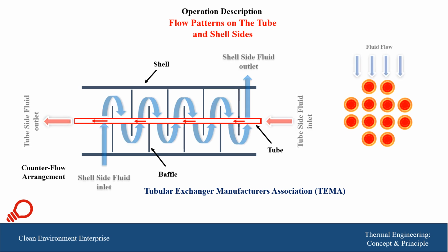Especially the thicknesses of these parts of the heat exchanger, which is composed of tube sheets, plates, the shell thickness, the tube, including the effect of corrosion, erosion allowances, and so on. Everything is put in a standard of TEMA.